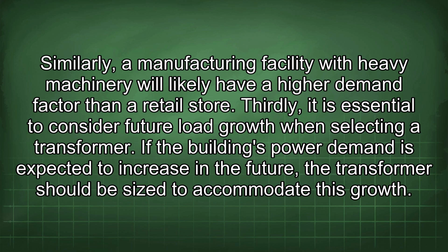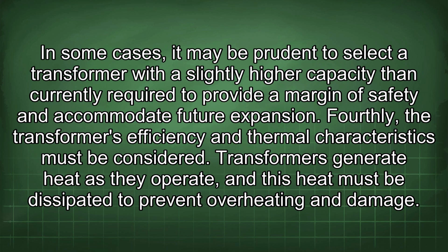Thirdly, it is essential to consider future load growth when selecting a transformer. If the building's power demand is expected to increase in the future, the transformer should be sized to accommodate this growth. In some cases, it may be prudent to select a transformer with a slightly higher capacity than currently required to provide a margin of safety and accommodate future expansion.